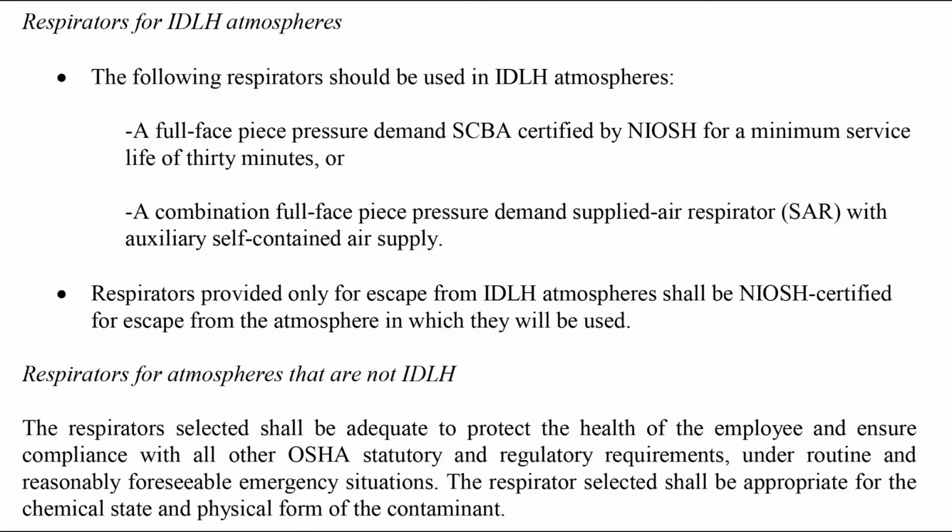Respirators for IDLH atmosphere. The following respirators should be used in IDLH atmospheres. A full-face pressure demand SCBA certified by NIOSH for a minimum service life of 30 minutes, or a combination full-face piece pressure demand supplied air respirator, SAR, with auxiliary self-contained air supply. Respirators provided only for escape from IDLH atmospheres shall be NIOSH certified for escape from the atmosphere in which they will be used. Respirators for atmospheres that are not IDLH.